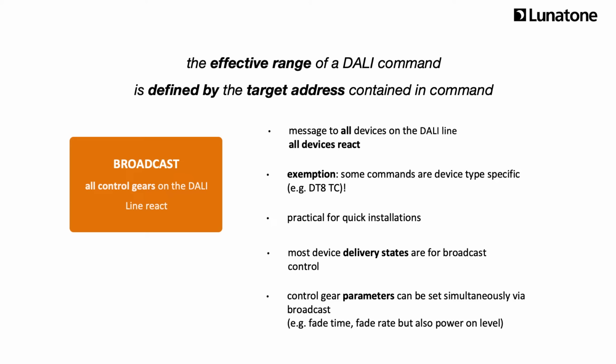Furthermore, DALI broadcast commands can be used to set DALI parameters for all the connected control gears. For example, the power on level and the fade time can be set like that, but more about this later on.